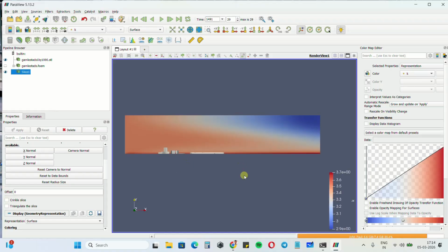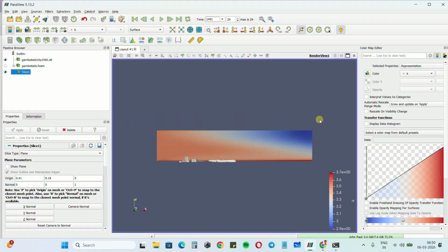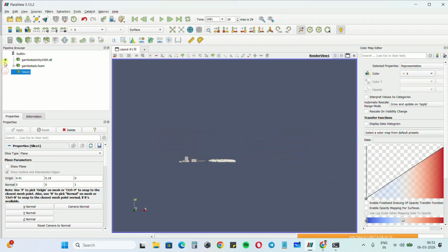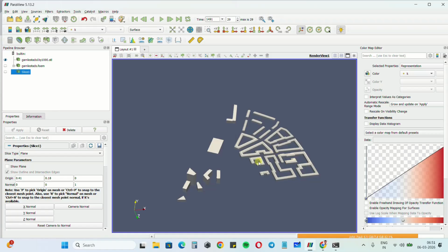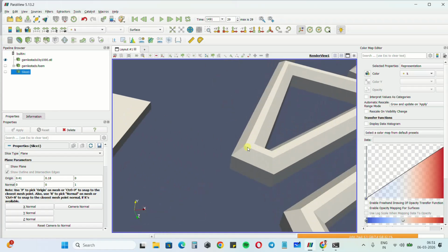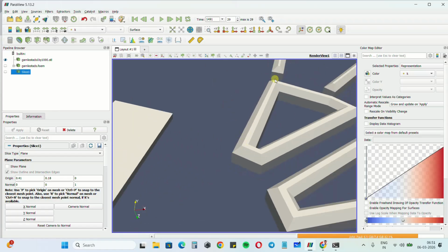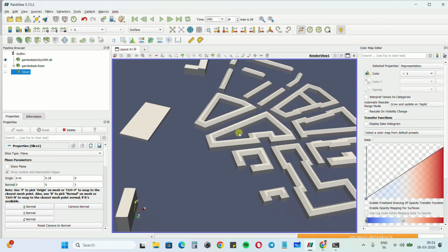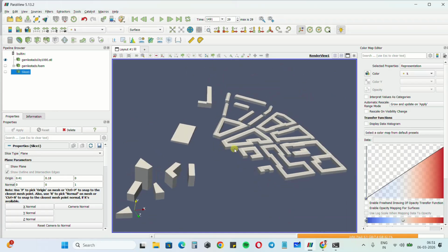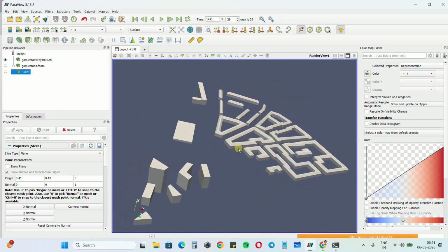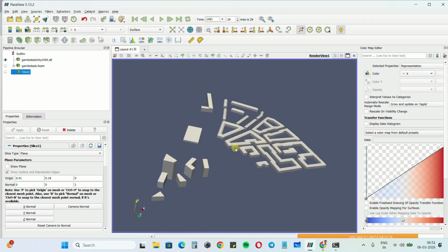So now let's edit the snappyHexMesh file. Before snapping, we want to do the surface feature extraction step. In contrast to the single building case, we have a relatively complicated geometry with a lot of feature edges, especially this chamfer. I want to resolve this sufficiently, and with this many elements in the geometry, it's better to use the feature extraction step. We have to do that before setting up the entire snappyHexMeshDict file.